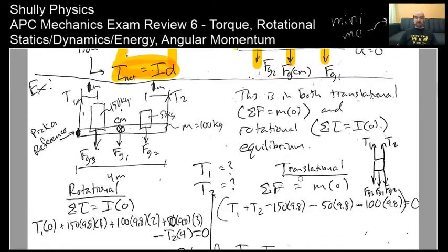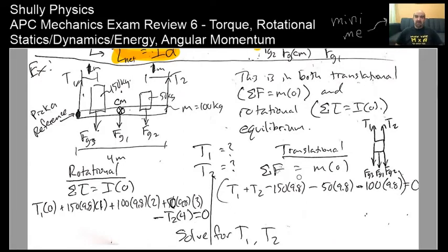All right, so here's some specifics. This is rotational statics and dynamics right here. That's what I was referring to in the title. So if we do have that object of 150 kilograms, the center of mass of the beam, which is 100 kilograms, is located at the center. If a problem ever gives you the mass of an object like the beam, but doesn't say anything else, then you assume that it's a uniformly distributed mass, and that means this 100 kilograms of mass can count at the center of mass. So on your force diagram, that's where you would apply that force.